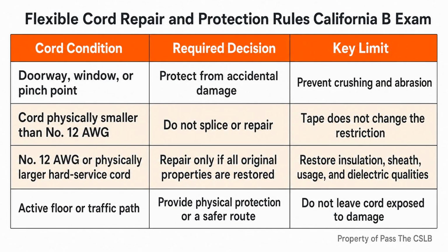I do not judge this by whether the cover looks sturdy from 6 feet away. I look for the correct listed and identified cover for the location. I also look at the box, cord entry, and condition of the enclosure. A proper cover does not make a cracked box or damaged cord acceptable.